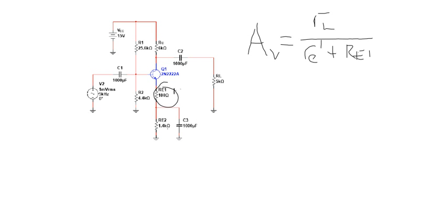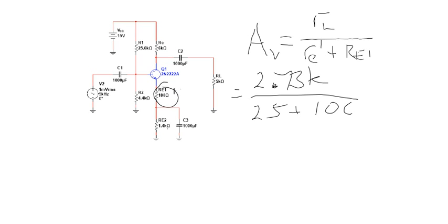That was the same numbers we had before, except now we have this extra 100 ohms down here. And that gives me a gain of about 23 now instead of 21.8. So I guess we call that 22. That's not an atypical gain for an amplifier. Sometimes that's good.